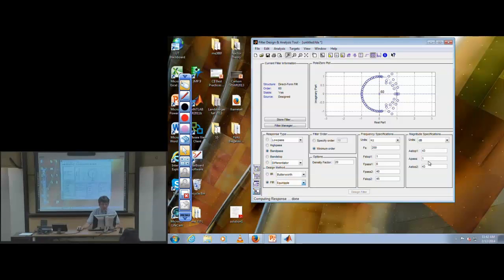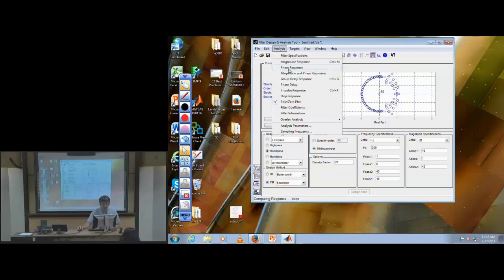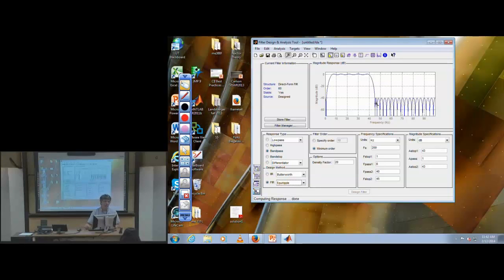It doesn't do a very good job at meeting the magnitude response specification at the stop band frequency. So we can trick the algorithm by moving the stop band frequency into the transition band, say 43 hertz or 44 hertz. And then actually we'll get the filter order down, surprisingly. And then last is the Kaiser or window method.